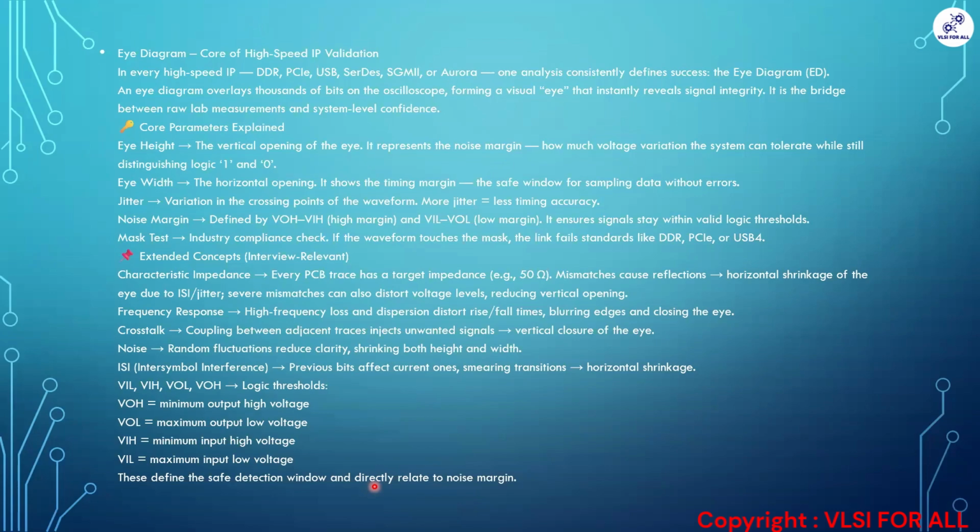Later, we use the clock recovery option, and we calculate the exact ideal bit rate of the signal you are working with. You have to set auto scale mode in the oscilloscope and analyze the real-time eye clock recovery data rate.